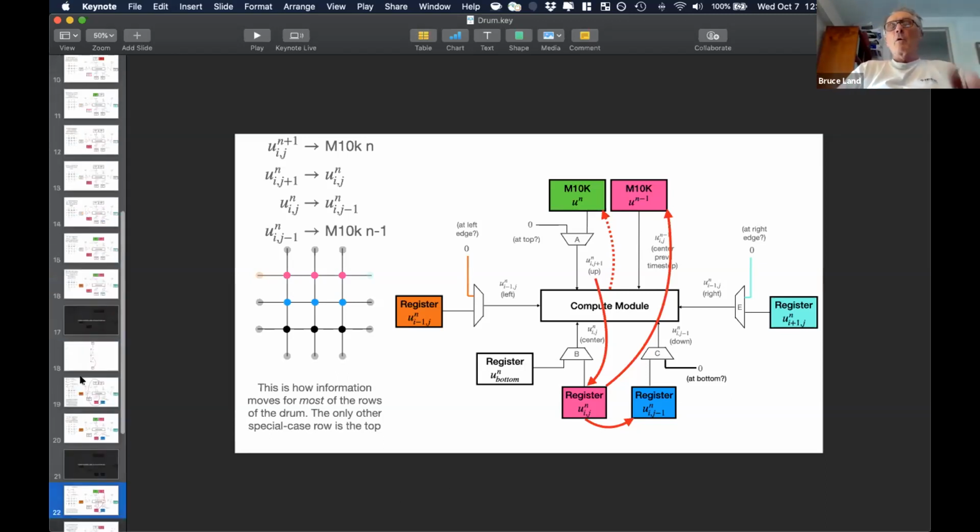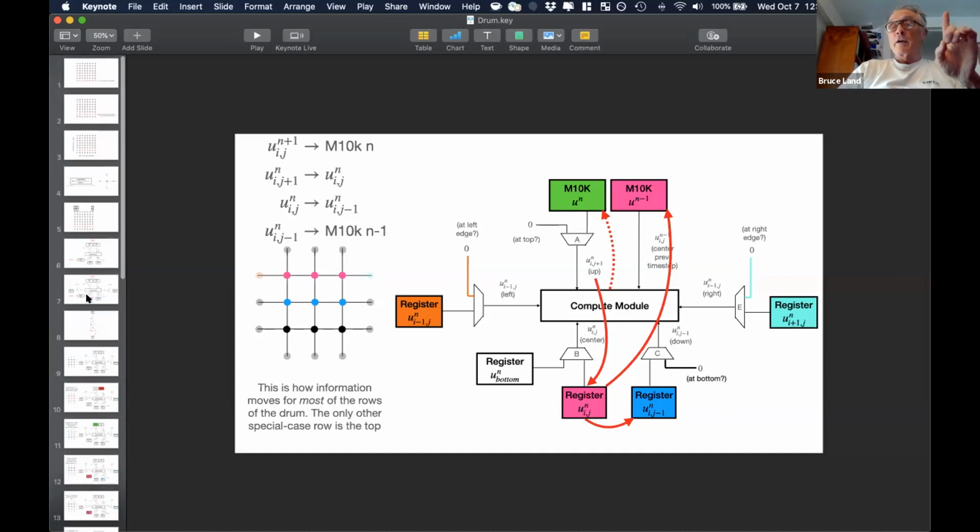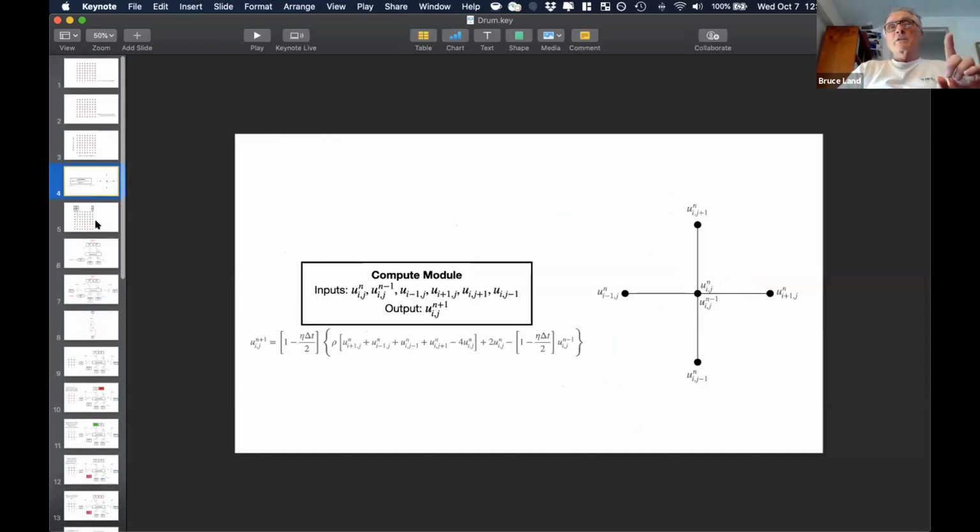So increasing rho up to 0.5 increases the frequency, and just below 0.5, where the system is still stable, you will find that the frequency is at the Nyquist maximum. In other words, there's 2 samples per sine wave cycle. It goes high, low, high, low, high, low. In other words, it looks like a square wave, not a sine wave.